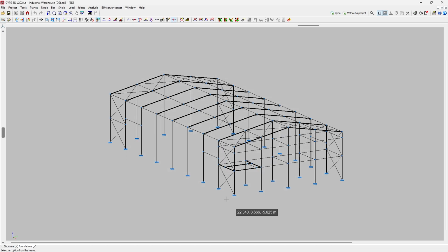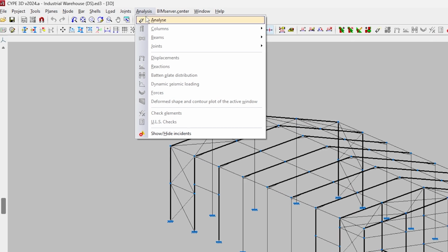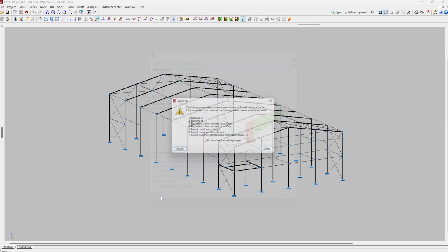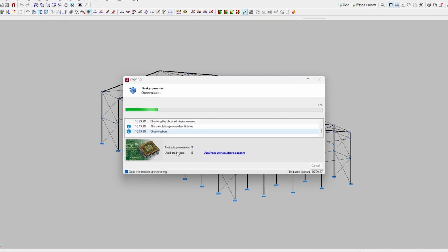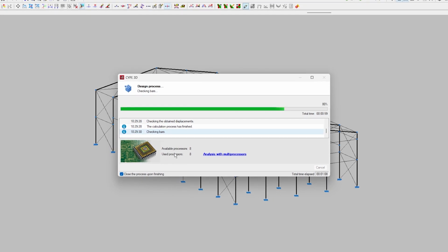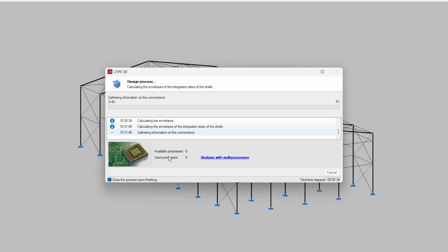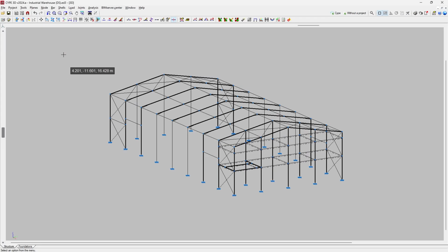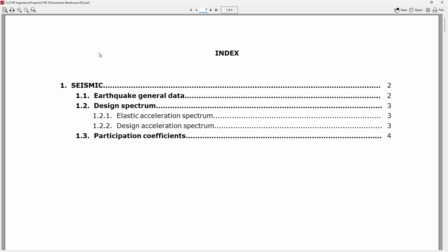If we have completed the definition of the model, we click on Analysis. The program carries out the seismic analysis by means of a complete spectral modal analysis that solves each mode as a load and carries out the modal expansion and modal combination to obtain the forces. Once the model has been analysed, we open the Analysis menu and check the specific report with the information about the dynamic seismic loading provided by the program.